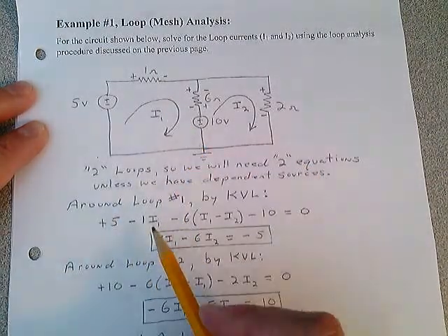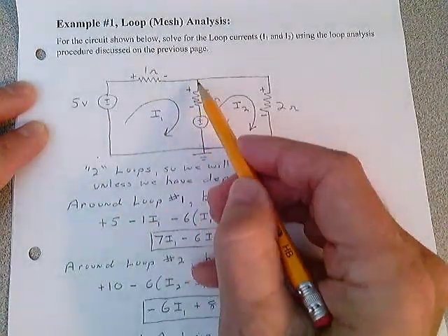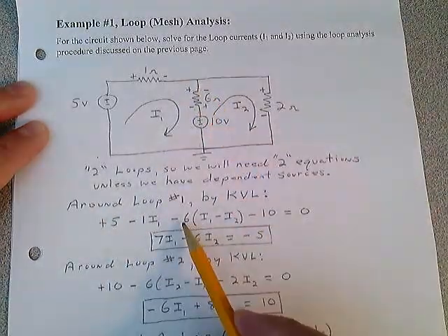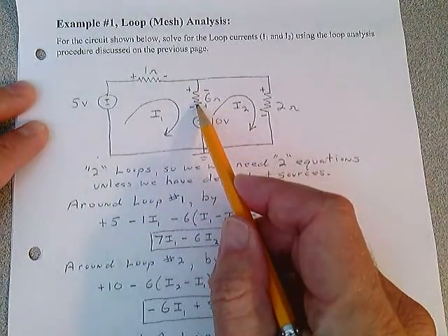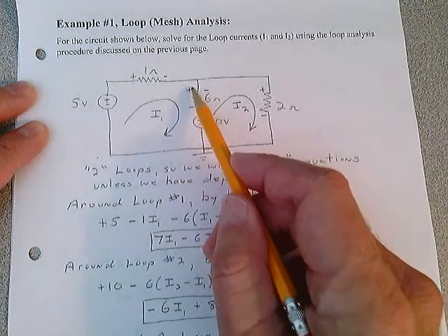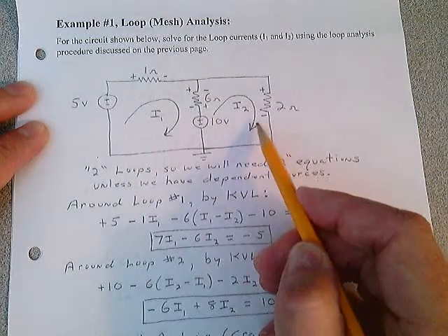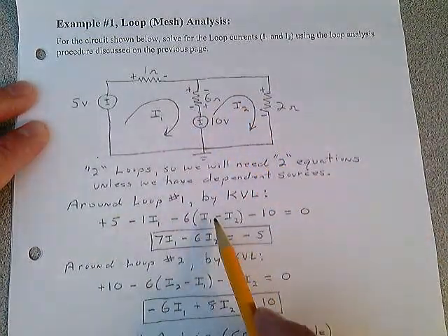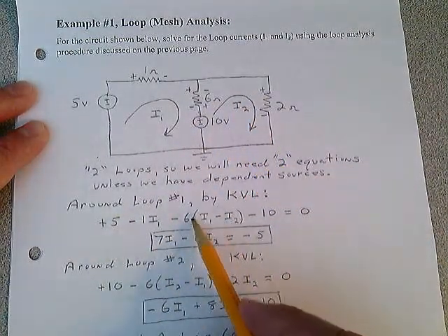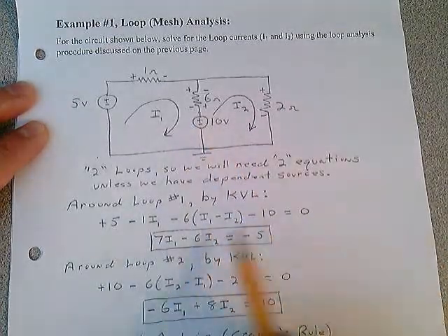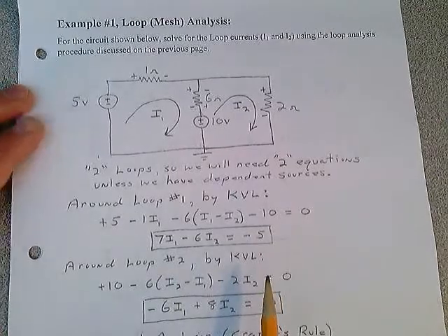What is the current? It's I1. Then you're down here. Minus 6, right away. Minus 6. Then you stop and think, what current goes through there? The lead current is I1. There's your plus to minus for I1. And then you subtract I2 because it's in the opposite direction, with the parentheses. Minus 10 equals 0. You clean it up, and there's your first system equation.